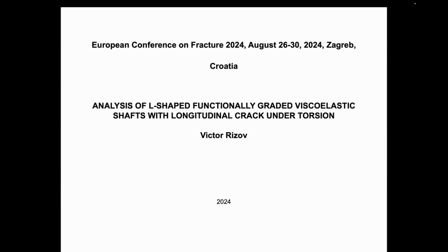For the crack, the strain energy release rate is derived. The time-dependent energy balance is analyzed for verifying the solution of the strain energy release rate. The influence of various factors like the shaft geometry, parameters of loading, variation of material properties along the cross-section radius, and rigidity of the spring support are studied.